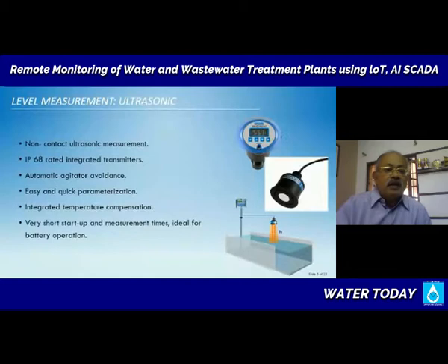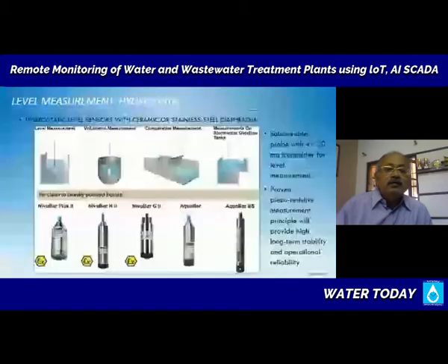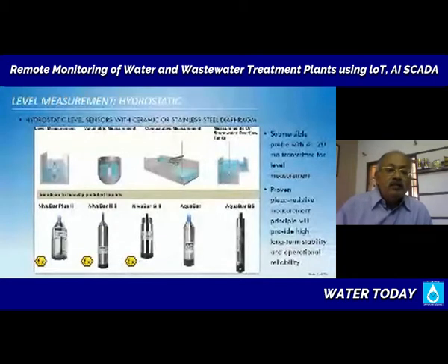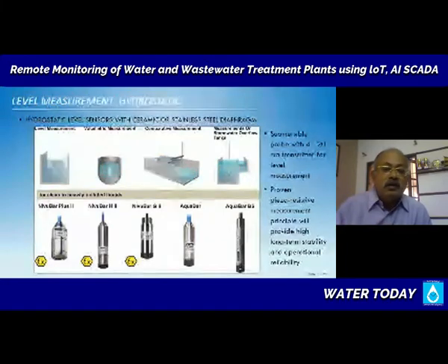And of course, there are other ways which could be looking at the pressure, hydrostatic head. So, seeing two sets of pictures. Above, you are seeing a plant process installation, and down below you are having a closer look at some of the sensors that are involved. Now these are all measuring hydrostatic head of water above the sensor. So if you're having 2 meters of water above the sensor, then the instrument will measure those 2 meters of head as a function of the pressure.